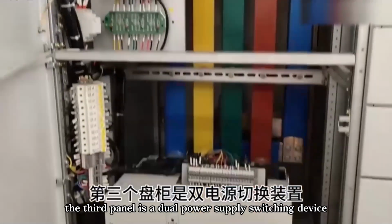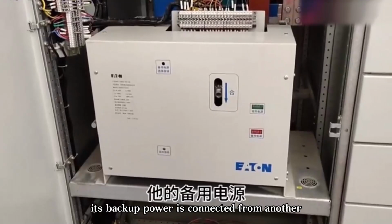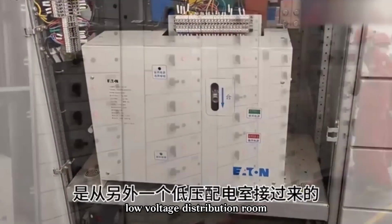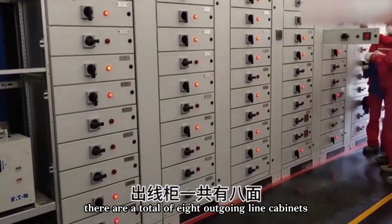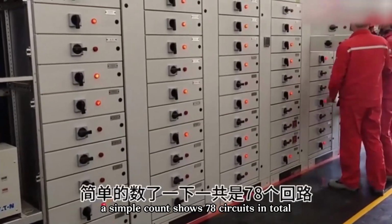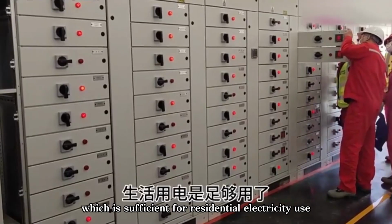The third panel is a dual power supply switching device, also called an ATS device. Its backup power is connected from another low-voltage distribution room. There are a total of 8 outgoing line cabinets. A simple count shows 78 circuits in total, which is sufficient for residential electricity use.